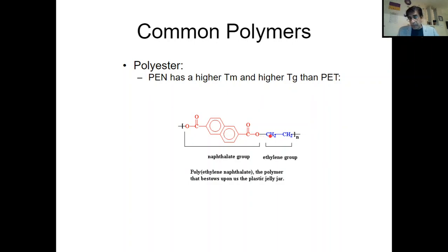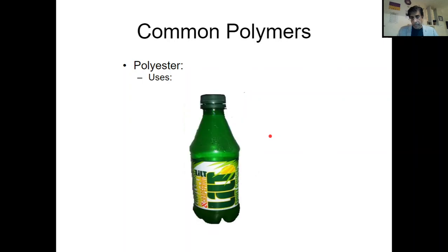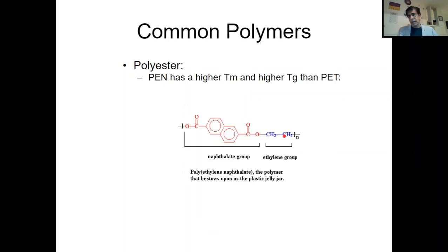Similarly, if you increase the number of carbons here, like 2 carbon, then 4 carbon, 6 carbon, and 8 carbon, this aliphatic chain will act as a plasticizer. You learned about the plasticizer, something that can soften the molecule, but this is already attached, so it is not the plasticizer as I discussed before. This is a covalent bond, so this is called an internal plasticizer. As the aliphatic chain increases, it acts as an internal plasticizer, and that is how it softens the